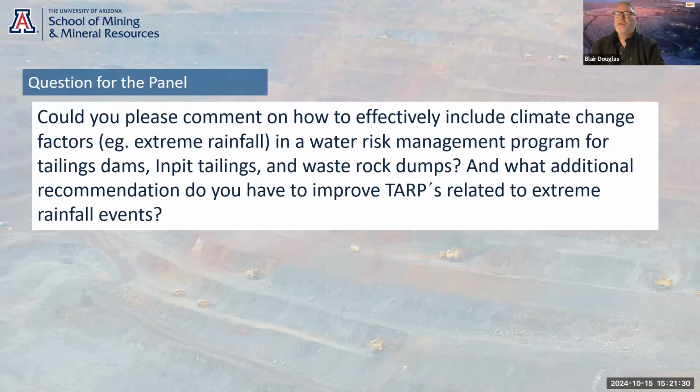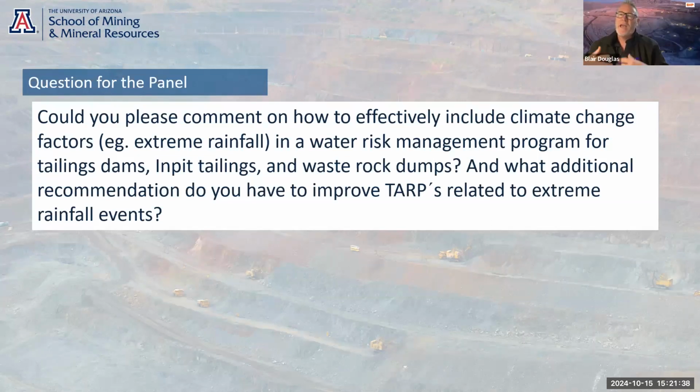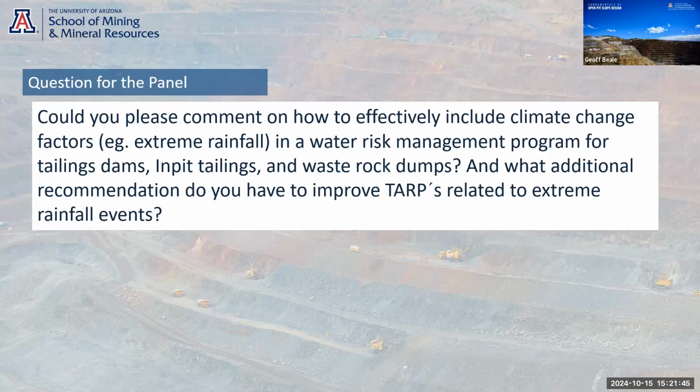The in-pit one, though, is interesting, isn't it, Jeff? Because we are looking for tailings deposition, you need consolidation, and whether you're getting under drainage is important. Because if you're not getting any outflow of the system vertically downward into the groundwater system, in-pit tailings will then remain saturated. And although that's probably not problematic from an environmental component, stability, probably not, there's human health and safety factors long term about having a pit full of sloppy tailings that's not draining.